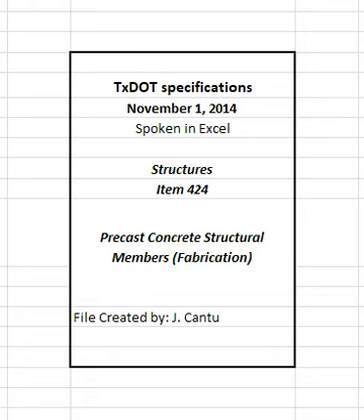Maintain concrete temperatures between 50 degrees Fahrenheit and 150 degrees Fahrenheit during the curing period. The maximum allowable concrete temperature may be increased to 170 degrees Fahrenheit if the contractor uses one of the concrete mix design options listed in Section 421.4.2.6, Mix design options, other than options 6, 7, and 8. The engineer may require lowering of the total cementitious content in the concrete mix design to the limits specified in Item 421, Hydraulic Cement Concrete, for repeated violations of the maximum curing temperature.